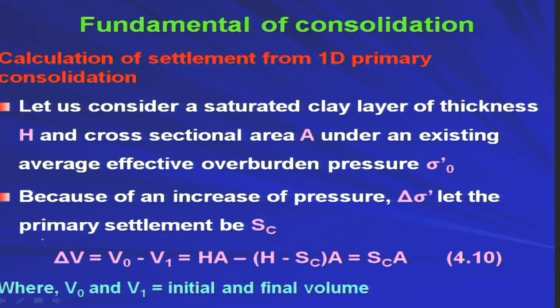We have already discussed this in the last lecture, because you are providing confinement in the lateral direction. So, H minus SC is now your new thickness of the soil deposit, where SC is the settlement, that means the deformation or the change in thickness. H minus SC into A gives me the final volume V 1, which gives the final expression SC into A. So, SC into A is nothing but delta V, the change in volume.